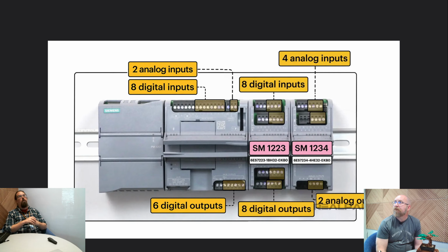There are also other power outputs on that power supply, so you could wire this to another PLC, for example, or use it to drive other things. Typically, you would not do that. The best practice would be that inputs get their own power supply, outputs get their own power supply, and your PLC also gets its own power supply. That's for signal integrity reasons.